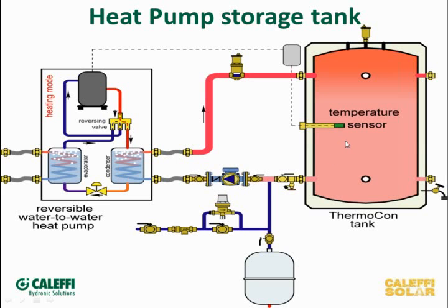And it shows it going over to a buffer tank. Now that's important. If your load and your source side don't exactly match, it's a good idea to have a buffer tank so that this pump isn't short cycling every time it kicks on and off. So we make a tank available for that in a bunch of different sizes that makes it really easy to do this.